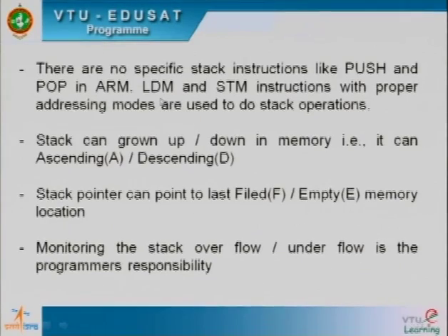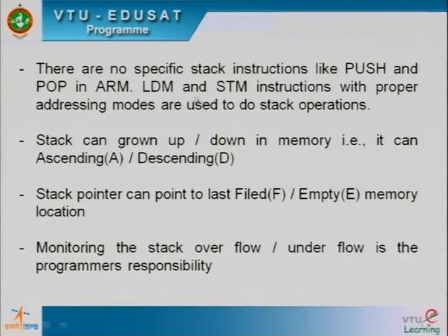But let's look at this. LDM and STM instructions with the proper addressing modes are used to do the stack operations. So there are no separate instructions. The LDM and STM instructions themselves do the stack operation with the proper addressing modes. What are these proper addressing modes? We'll look at that in the next slide.